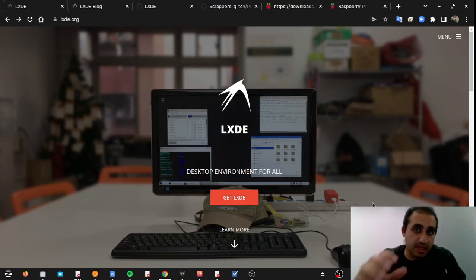You can also tweak the Kiosk system to use the system resources such as Wi-Fi, Bluetooth, or any other sensor connected to your device. On the Raspberry Pi, there is another benefit: you can control a GPIO when the system starts. You can power a device, you can power your custom hardware when the system starts. You can run custom code when the system starts, or you can run an application that dispatches other code to start the custom hardware, or to start controlling the GPIO.